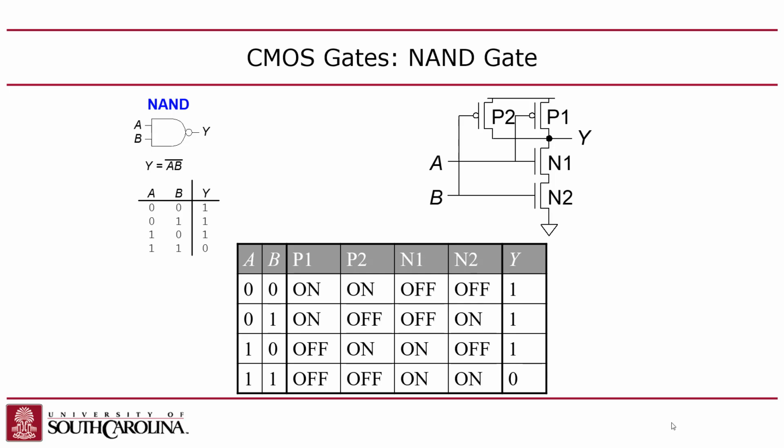Yeah, exactly. You can add an inverter and create an effective AND gate, but you can't build a single structure. You can't build a single gate that's an AND gate in CMOS. It's impossible. Likewise, the buffer I showed you too, same thing. You can't build a buffer either.